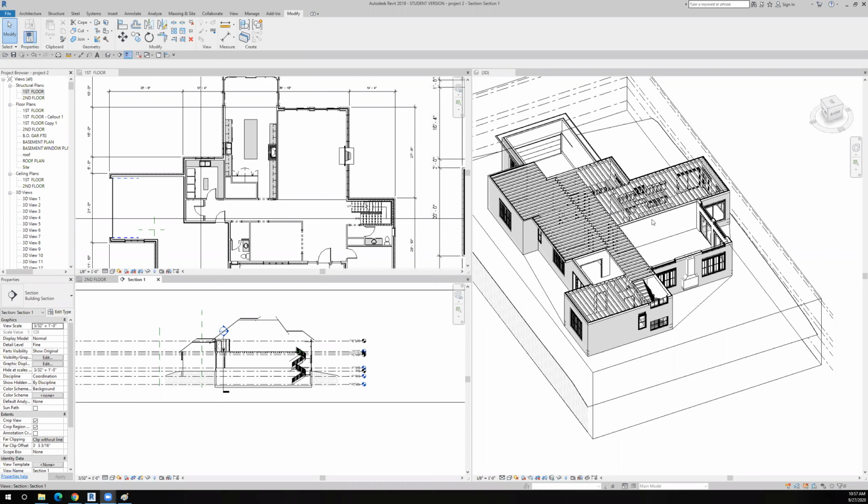Now, in order to carry the weight of the wall, all of the loads that are coming down on that wall, we either put a wall in the basement to transfer those loads to the footing, or what's more typical is that we put in steel beams to carry those loads, so we have a wider open space in the lower level. So let's take a look over here.